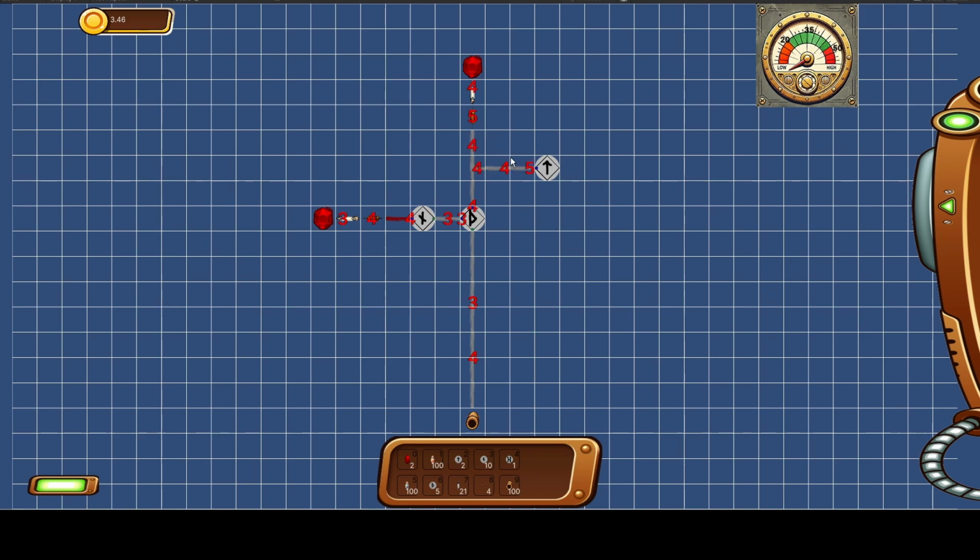And what it means is that when these charges go to try to move through one of these conduits, they are dissipating energy. That is what your resistance does. It takes some of the energy from the current and puts it out as heat. Now, how it dissipates it is complicated in real life, and I didn't simulate all that. Instead, I just wrapped it up in a nice little number I call power dissipation. So I say they all have a power dissipation of 5 watts. That means they can somehow, some way, get rid of about 5 watts of continuous power without heating up.